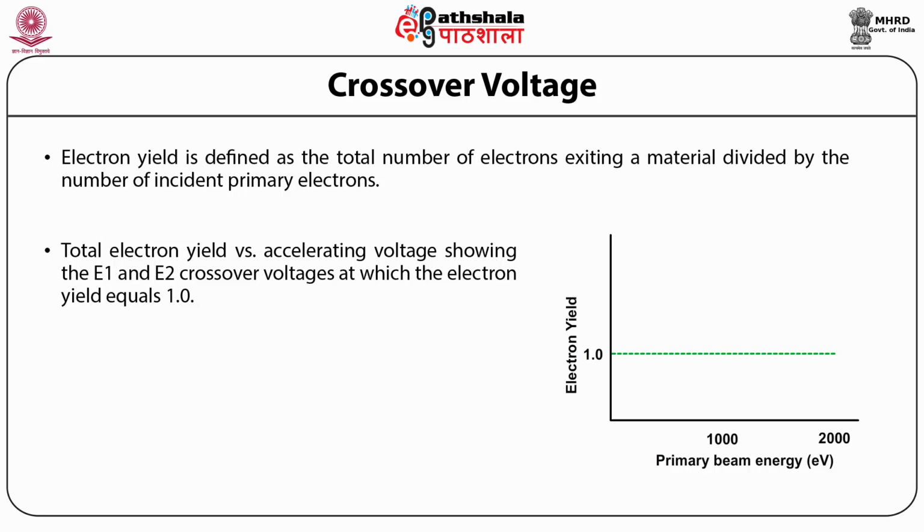The negative charges build up within the coated specimen, which behaves as an insulator and displays an edge bright region in the image. Negative charging can produce fields large enough to deflect the incident electron beam away from the sample or even back up the microscope column,